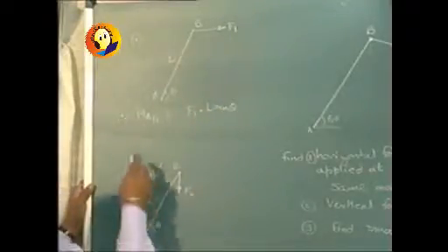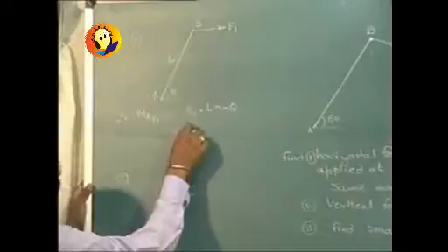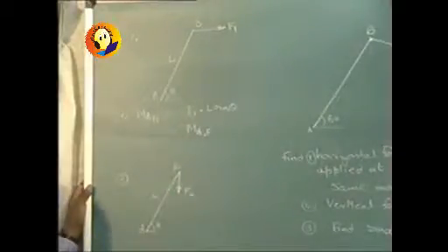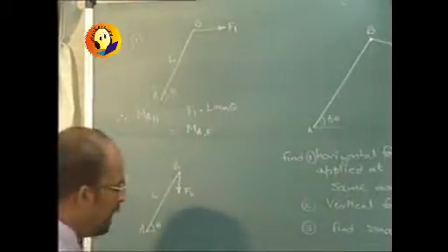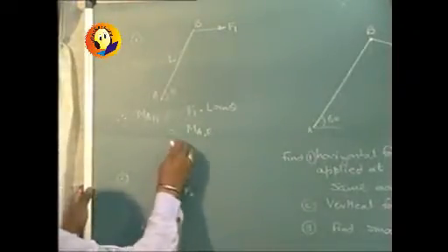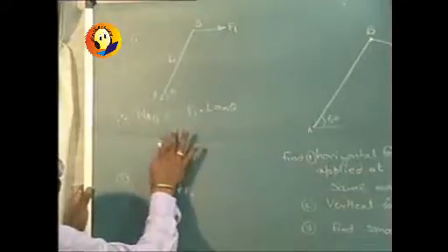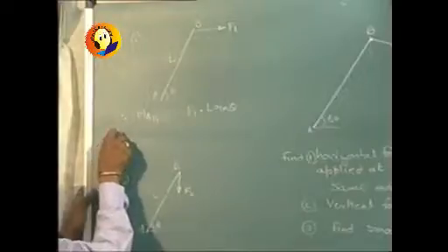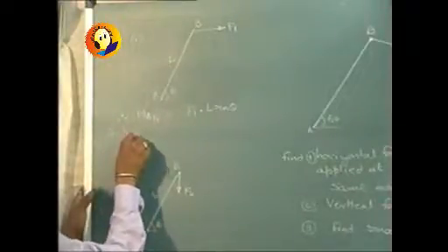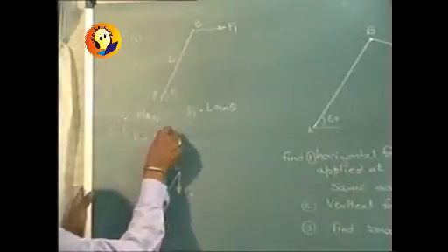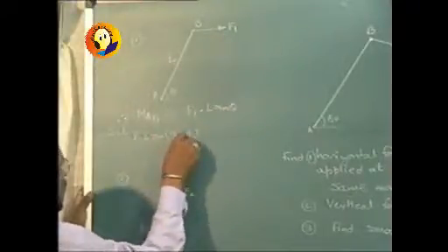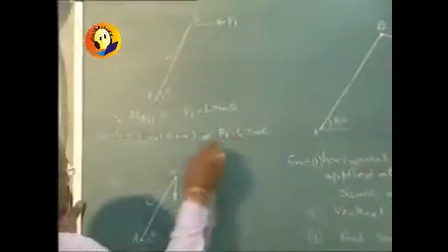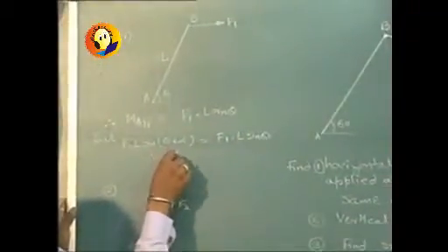We already have this equal to the moment about A of that force F, which we have already calculated, or we can simply equate the previous answer. We can say that the moment of F1 about A is F1 into L sine theta, but F into L into sine of (theta plus alpha) is equal to F1 into L sine theta, and therefore F1 can be calculated.